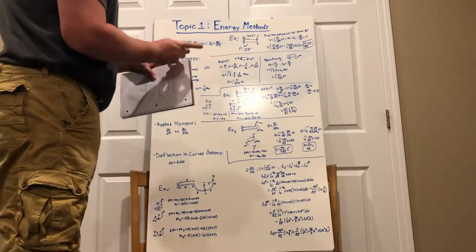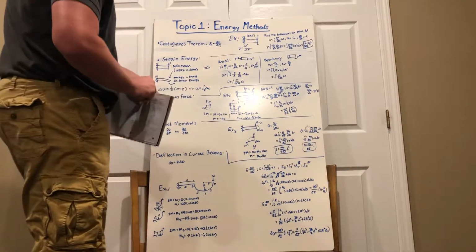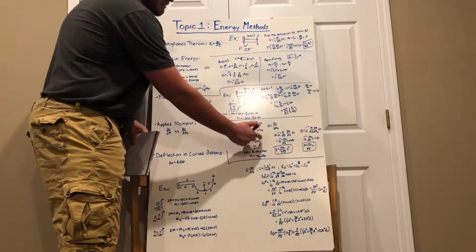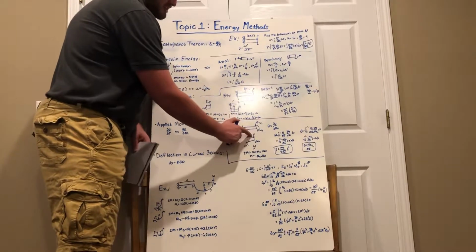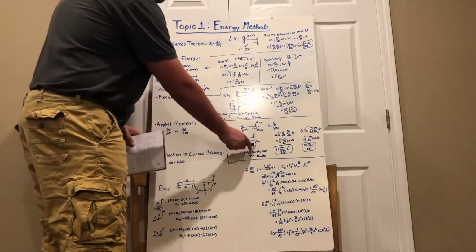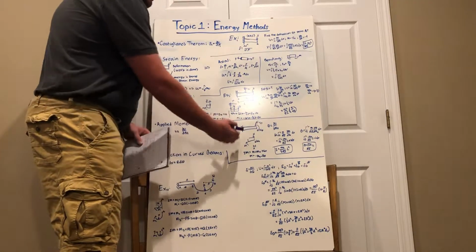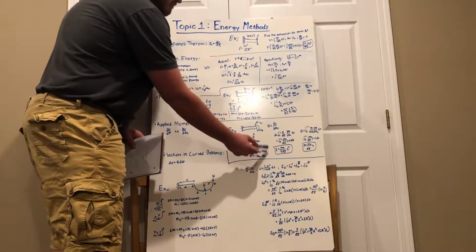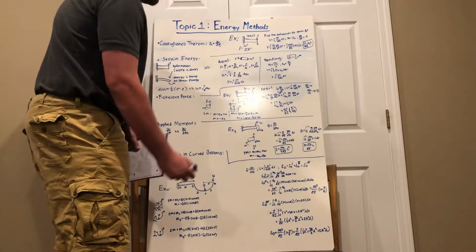Now, let's draw a free body diagram. So here's our free body diagram. We're going to have our moment that's being applied, our fictitious force, and our moment that's being caused. And we're measuring from the right side in. So let's sum the moments. Summing the moments will give us m plus this initial moment plus this q times the distance x.